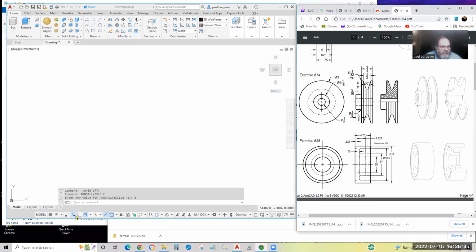Now I'm trying to get used to dynamic input, so I got that turned on. Polar tracking is set for 90. I got burned having it set for 45 for 3D work. I'm going to keep object snap tracking on just to see if I can use it. Don't know if it's beneficial in 3D work or not. I got object snaps on and set to my 5 favorite. Freeze the screen here and make note of them if you want.